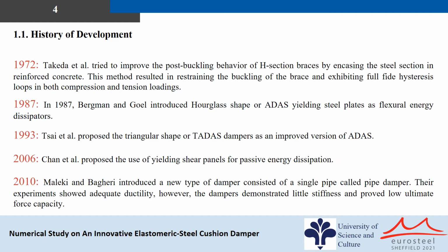In 2010, Maleki and Bagheri introduced a new type of damper consisting of a single pipe called pipe damper. Their experiments showed adequate ductility, however the dampers demonstrated little stiffness and proved low ultimate force capacity.